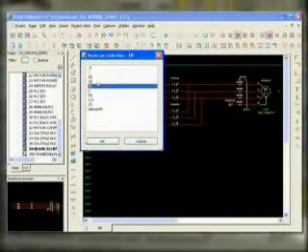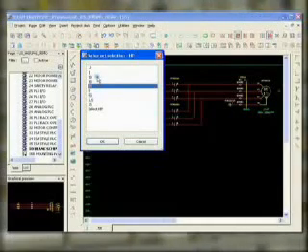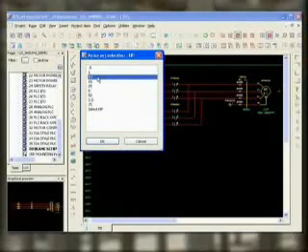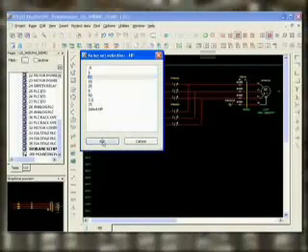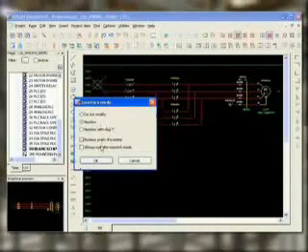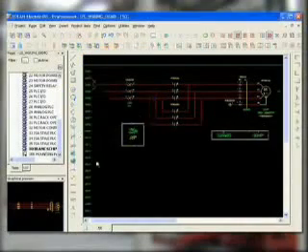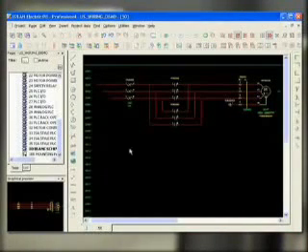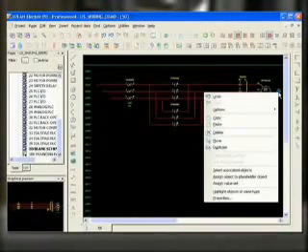When you insert a macro that contains a placeholder, a value set selection will appear. For example, the value set in this particular macro is based upon motor horsepower. The values of the wire gauge, fuse and motor have all been set. To change the value set,